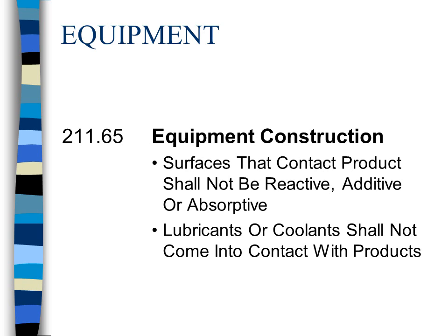Oxidizer, well, you're filling a liquid oxygen reservoir. So if you're not diligent in making sure that where you're filling that reservoir is free of contaminants, you may have two out of three in the triangle of fire. The third is an ignition source. An ignition source does not have to be an open flame.